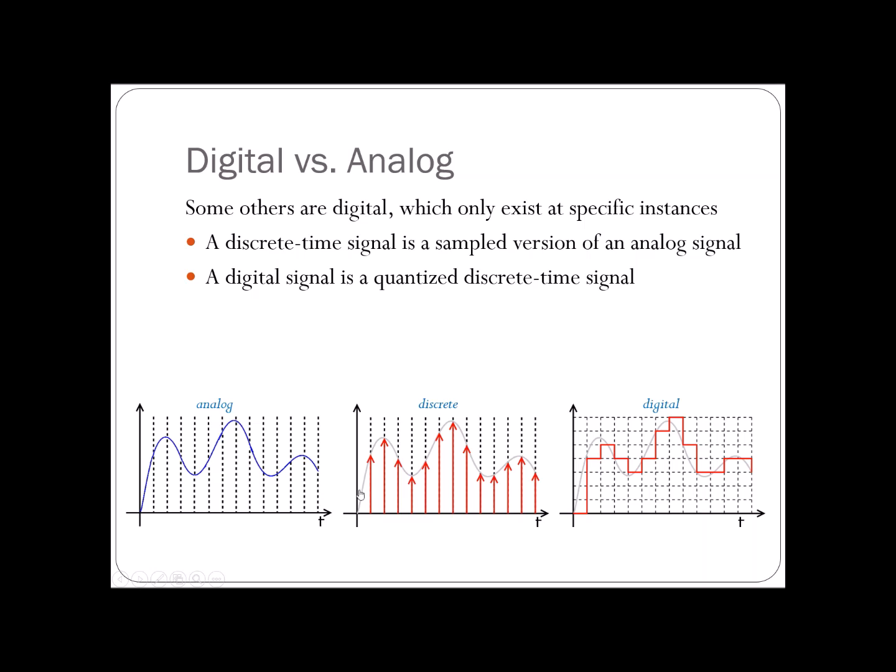What do I mean by discretized? You sample it at a regular interval. So if this is your signal, I redraw it again here. We discretize it, we sample it at a certain interval, and then you just record the value at the time instances where you sample it. So in this case, after you discretize it, you only have these discrete values. Of course, the shorter the time interval, the more your discrete signal resembles the analog signal. That is pretty intuitive, right?